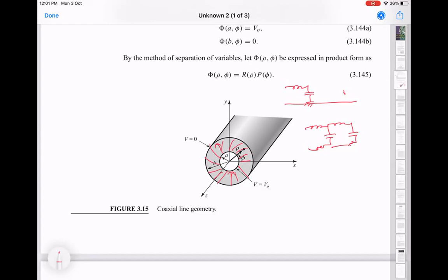So this basically tells you that the inside radius a, the outside radius b, and the epsilon r of the dielectric are what's going to tell you the properties of the transmission line. The conductivity will also play a role, but we are always going to be working in the low loss regimes.